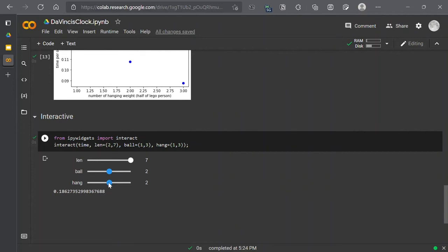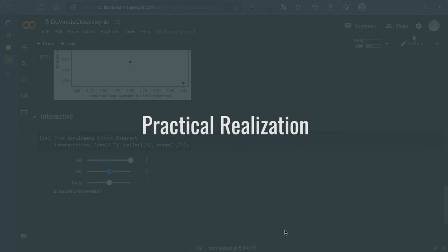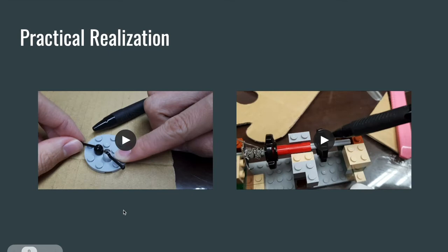That is for the Python simulation. After several tests, we couldn't make our clock move. The process only succeeded up to the weight dropping step. We discussed and had some conclusions. First, the angle between legs we put on the bottom of the rotary pendulum. Because this component is not fixed, the angle might increase during pendulum rotating. Thus, the legs will just get stuck in the teeth of the gear.